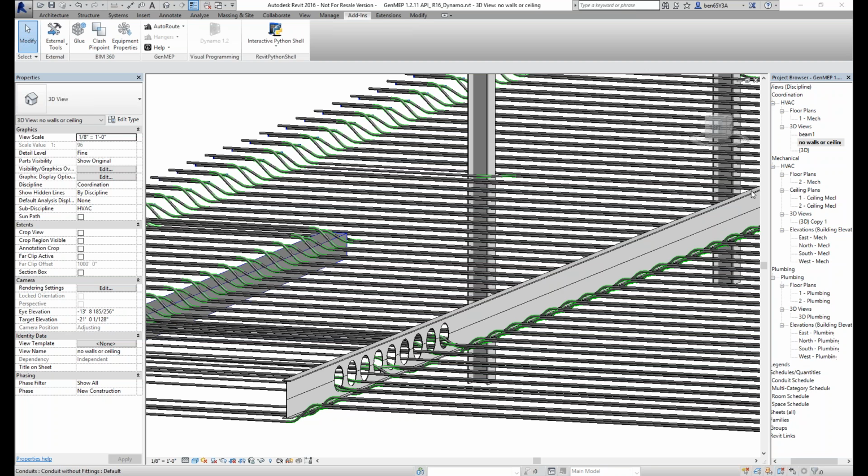Okay, so there are a couple of questions that have come in, and I'll start to address those. Could you use a combination of fittings, 90s and 45s, within one route? We currently allow for combinations of fittings when you have fittings that are changes in elevation and changes that are in plan. So if you only wanted to use 90s in plan to create an orthogonal route, but wanted to allow 22.5s or 30s, we have that functionality.